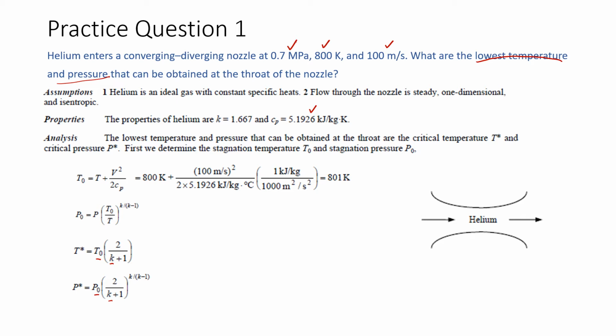I'm going to mention this again, that whenever you're dealing with a velocity, always remember to convert. When you have velocity and a unit of energy there, kilojoule, then you need to be careful, because V squared will typically give you joule per kg. So we need to get it the same unit as the specific heat dimension, which is kilojoule per kg times temperature here.